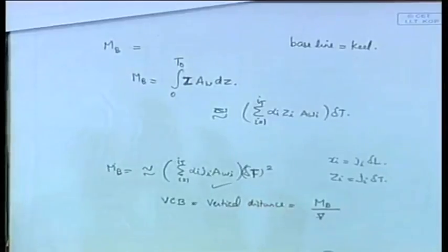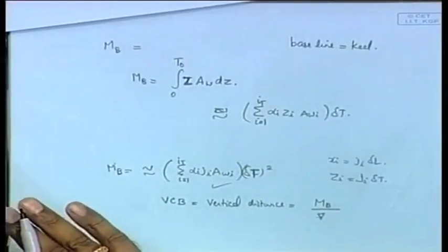What we have done is we have seen the basic idea is to calculate the moments, different types of moments, and moment of inertias we have calculated, which is again a moment only, second moment, about origin, about the baseline, etc. Either way you calculate the different moments, the areas, the moment of inertia, and you can calculate correspondingly the LCF, VCF, etc. as we have seen. So these are basically your hydrostatic calculations. We have kind of covered everything.